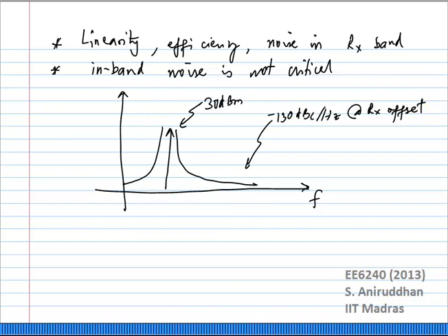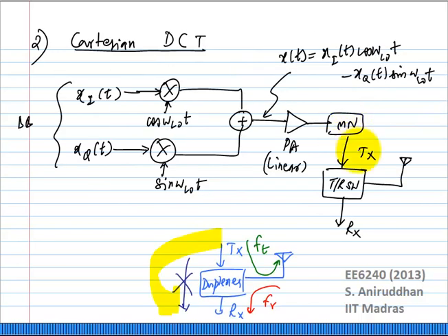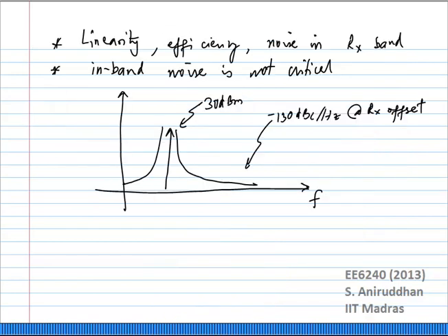Now this is on the transmitter side. If your duplexer has a certain rejection, then you will be okay. Because if the duplexer has 100 dB rejection, for example, then you have basically cut down this noise. Unfortunately, practical duplexers will have finite rejection ratios, maybe 40, 45, 50 dBc. So this may end up going to well below your receive signal.